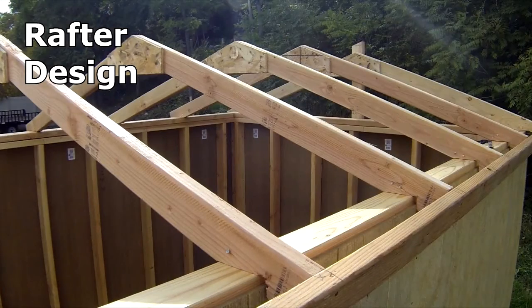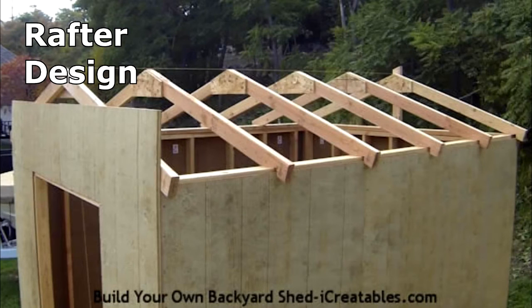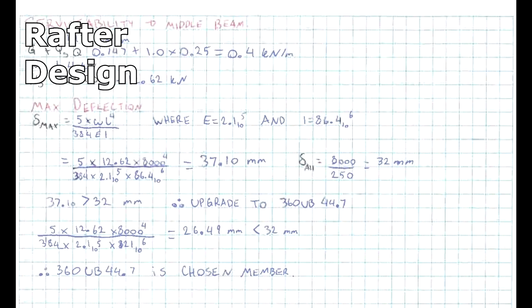Rafter design consists of firstly calculating dead load, live load and wind load, then calculating these figures into load combinations for the critical load. Once completed, rafters are then designed for pure compression to avoid buckling of members. Moment capacity, serviceability and maximum deflection are then checked to ensure rafters chosen are satisfactory for the structural requirements. Two rafters were designed, one that would go in the middle of the structure and one that would go on the edges of the structure.